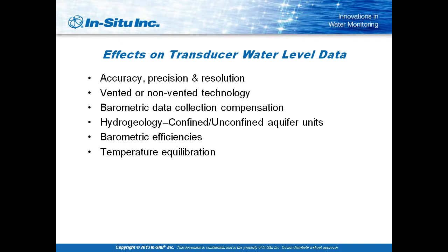Let me speak very quickly about that. All of these units basically have a pressure sensor and a temperature sensor on them. And as you know, temperature and pressure are directly related. So it's necessary that temperature reach equilibrium before you actually start taking your measurements. What I would suggest is that when you put a sensor, whether it's of my manufacturer or anybody else's, in the well, give it 10 to 15 minutes before you really start to read that data, because at first it'll be kind of choppy.